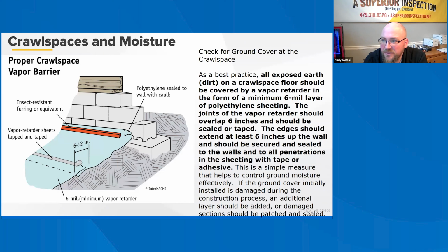Venting crawl spaces in humid conditions can cause condensation on cool surfaces, including ductwork and floor framing, potentially leading to water accumulation, wet insulation, material degradation, and mold. Ground cover laid on a crawl space floor can become damaged over time, reducing its effectiveness and making drainage difficult if wetted from plumbing leaks. As an enhancement, a mud slab, which is a 2-inch thick concrete slab, may be placed on the ground cover and sloped to drain to a sump pit for wet sites.